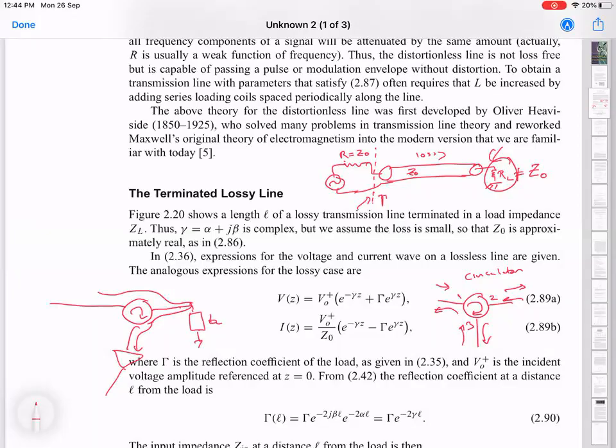But I'm not talking about filtering. I don't understand the question. Why are you asking about omega 1 versus omega 3? Because you told that you have the Johnson noise and you want to cut that Johnson noise to reach the source, right? Oh, but that is across all frequencies. So the attenuation which is going to be present in this part of the line is attenuating all frequencies in the same way. Because the simple model we use of Johnson noise is that it's a white noise. This has the same intensity at all frequencies.